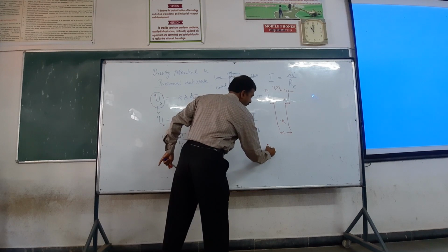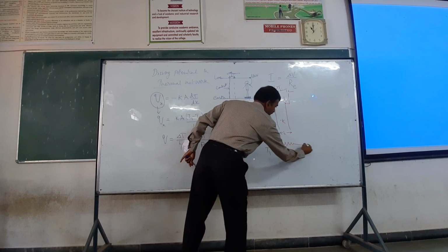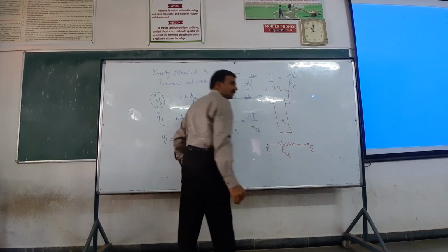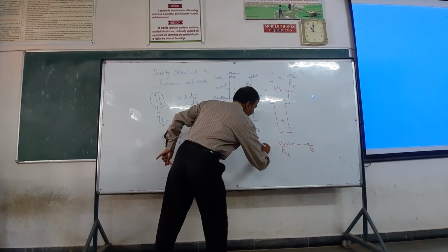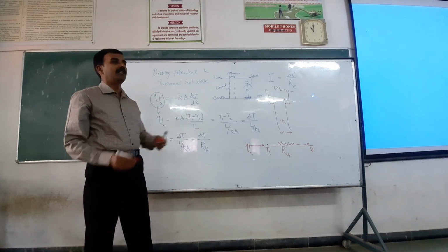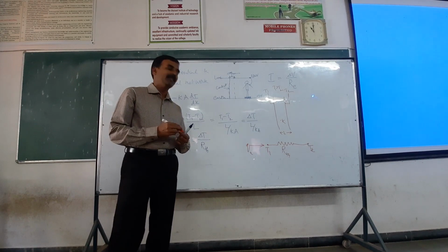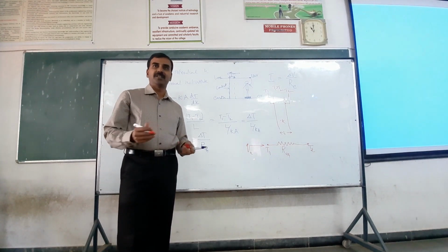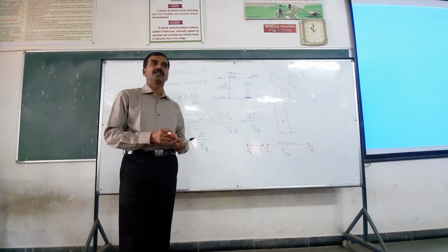See, there is T1, right? And between T1 and T2 there is a resistance. This resistance is thermal resistance. In this case, this is L by K, and your heat is flowing in this direction, say Q in the X direction. So this is a thermal network diagram, and this concept is applicable, right? See here, this is conductive resistance. Similarly, if it is convection, we will get convective resistance. Radiation, similar resistance, right? Just like we have electrical resistance there.